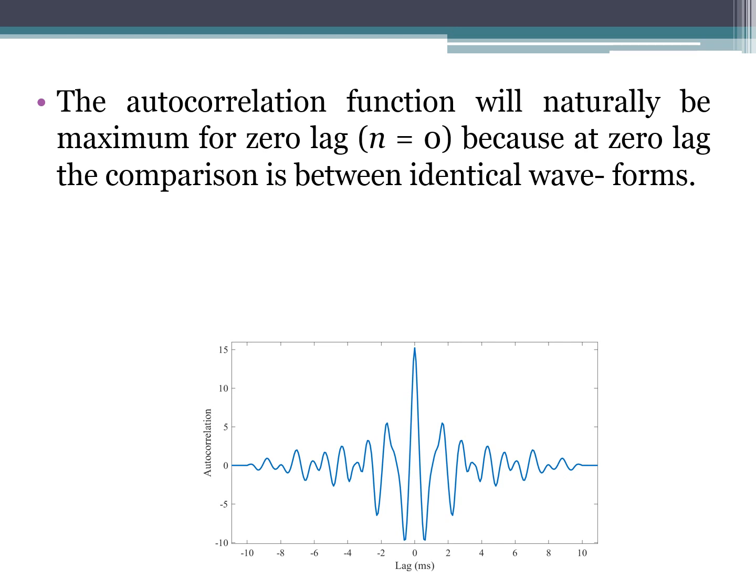Now there are some basic properties of the autocorrelation function. The first property is that it will be maximum for zero lag, because at zero lag the signal is compared with itself. Therefore, at zero lag you will find correlation maximum, and when we talk about the normalized coefficient, it will be 1. As you can see in this figure, at zero lag the value of correlation is maximum.